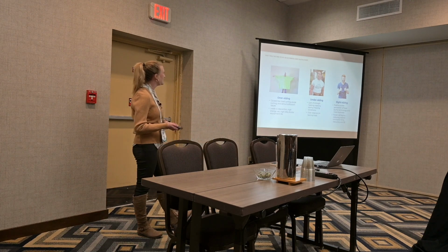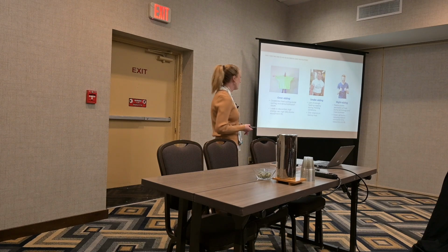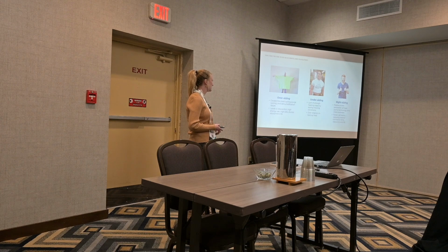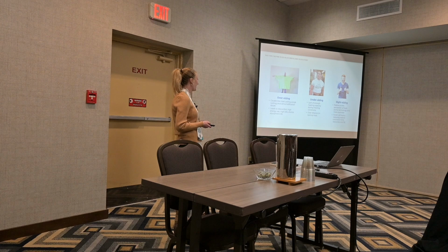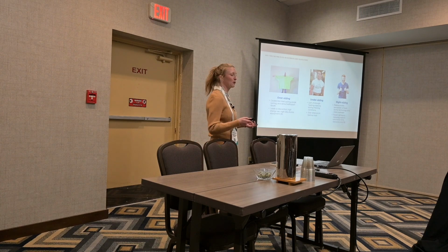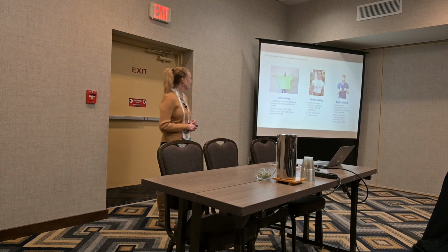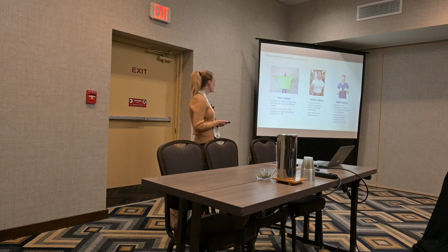So why take the time to do an accurate load calc when it comes to a heat pump? Oversizing is going to cause low load cycling, purge cycling, dehumidification issues, and lead to discomfort, high energy use, high bills, and shorter equipment life. You also don't want to undersize because it's going to lead to a lack of enough heating capacity during freezing conditions and over-reliance on backup heat.